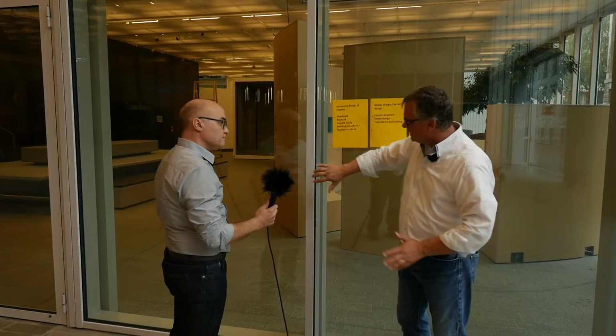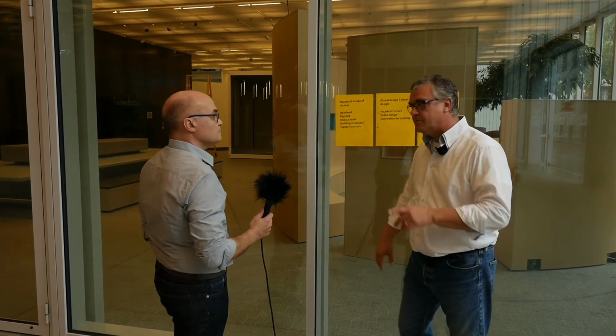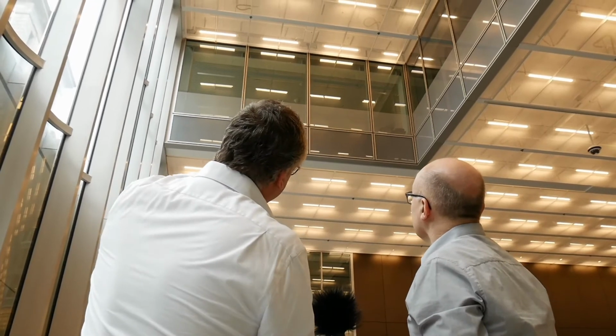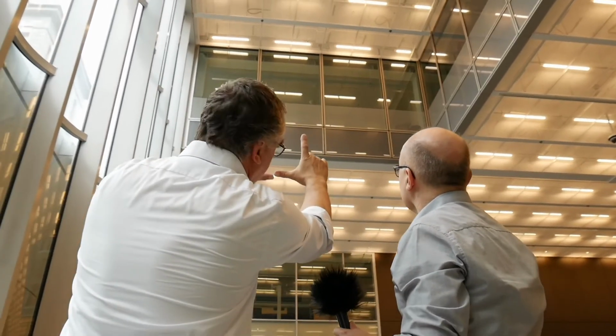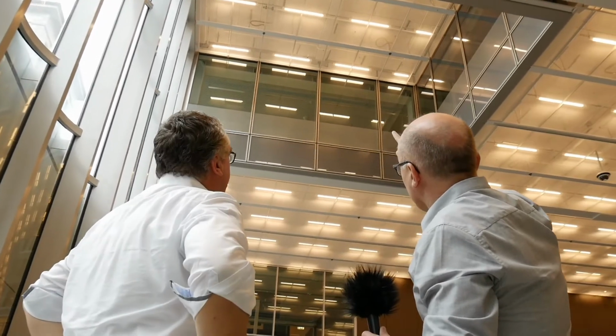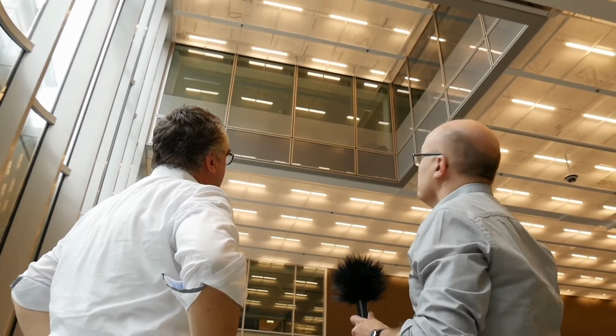The glass is brought in and then it's connected. And the unitized system, you said that's a unitized system. Yes, correct. So that comes as one block. The frame is brought in position, and it's simply hung and attached with those connections that we mentioned earlier to the top and the bottom of the floor.